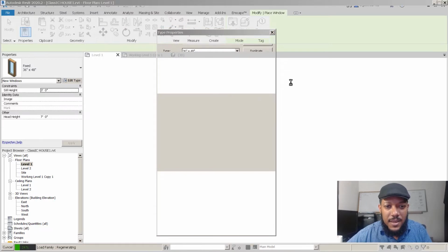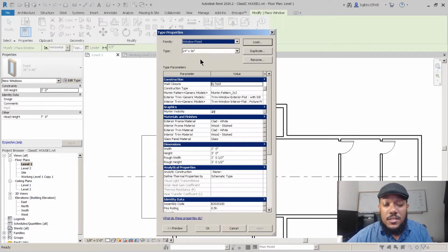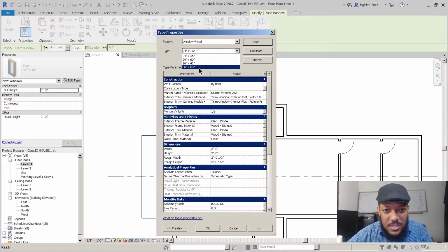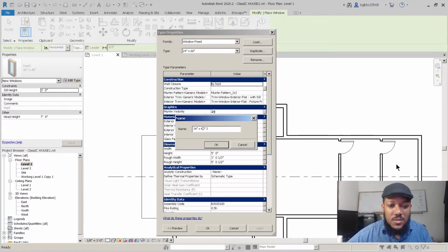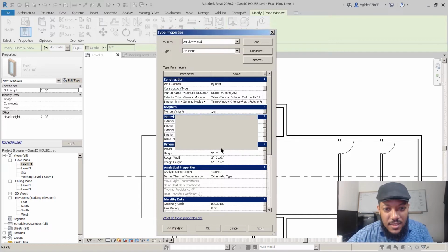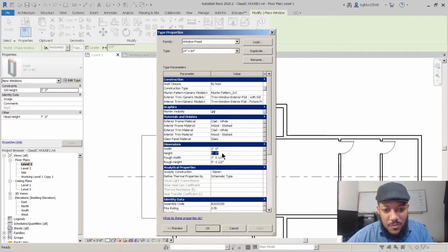So it's loading the families. It's the same family with different settings. And so you see that we have the 4 that we chose. And we're going to add some. So we're going to duplicate one of the families that we have here. And we're actually going to make it by 7 feet. So 7 feet equals 84 inches. So we're going to come and we look at the dimensions, and where it says height, we're going to put 7 feet.